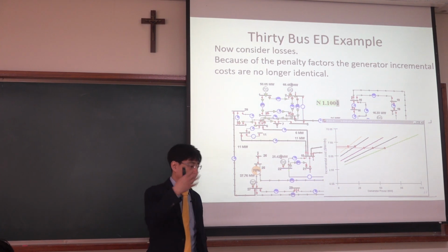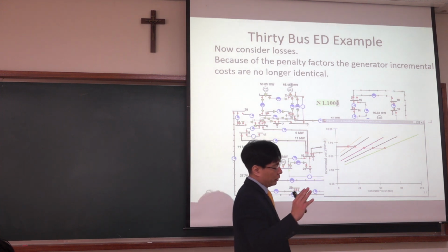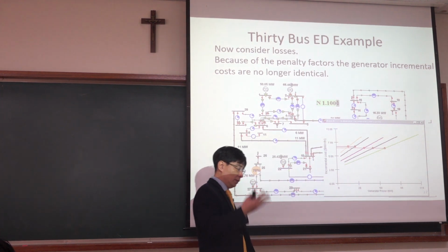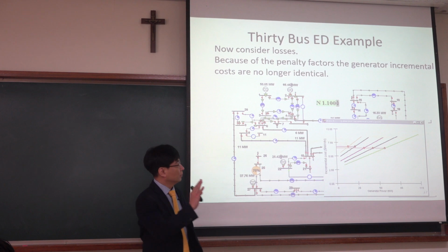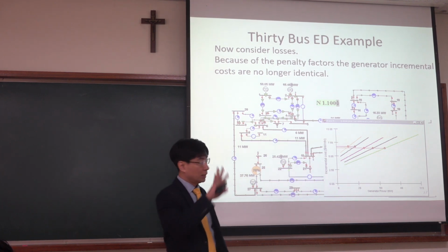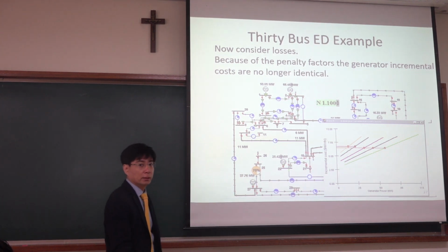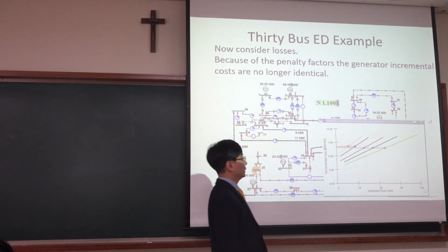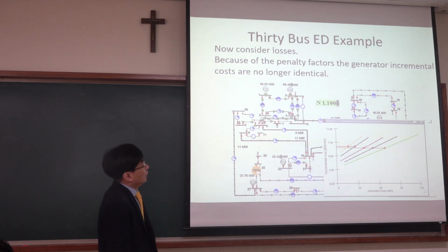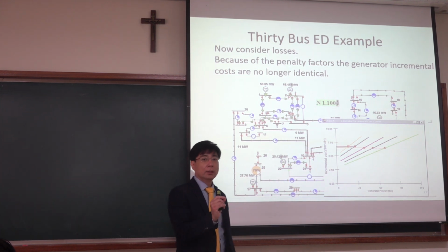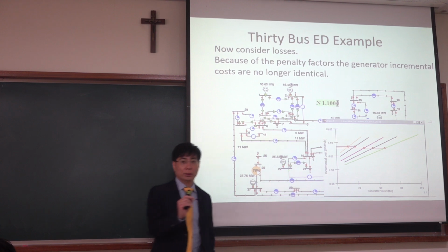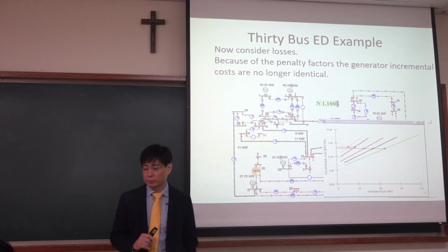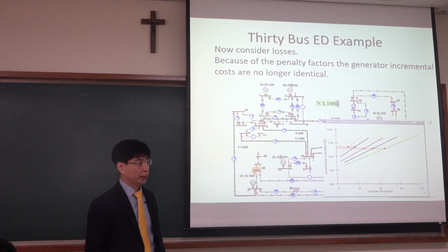Because if you want to use Newton-Raphson, you need to compute the Jacobian and take the inverse of that. But when the system is congested, the Jacobian condition number can be very huge, like 10 to the 6, 10 to the 7. So it is numerically unstable. That means feasibility is very important later when you solve optimal power flow using deep learning.